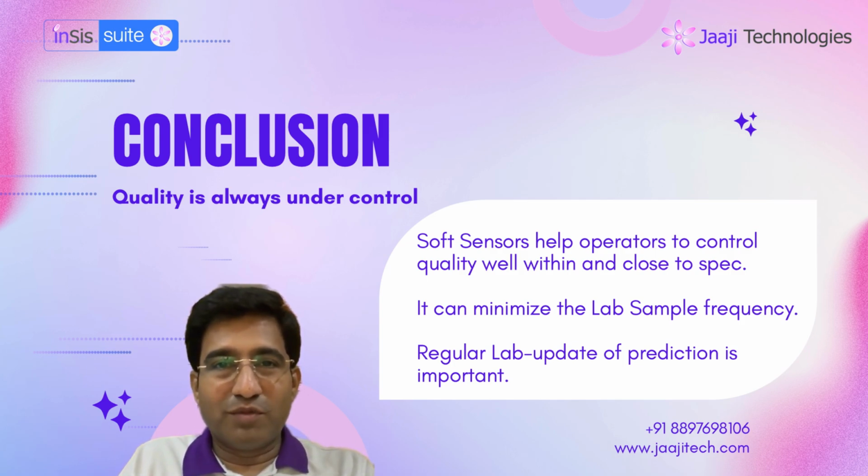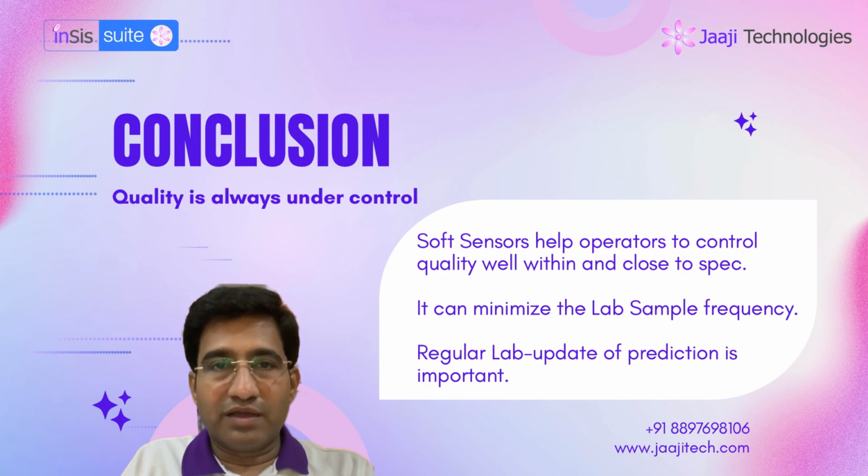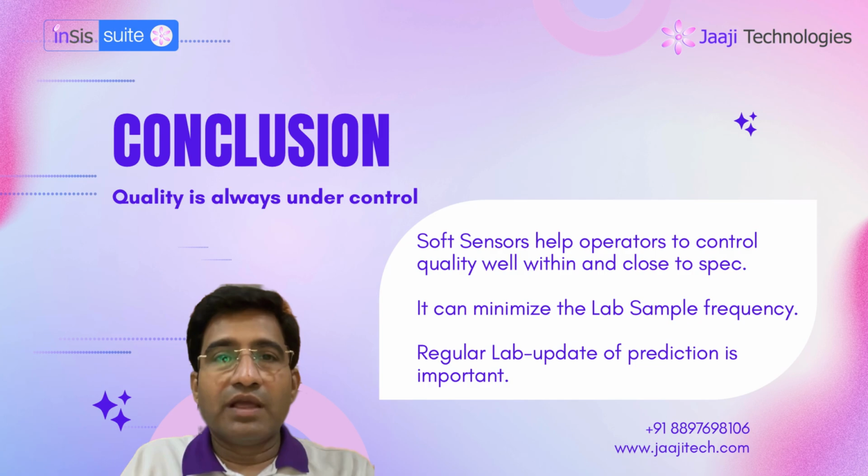So we have come a long way. We have learned what a soft sensor is, how it works, underlying technologies, methods and algorithms, platforms, and we've seen how to build it and deploy it using insys.ai. Now, to conclude the session, in order to effectively control the quality, soft sensors come very handy to effectively control the product quality. The accuracy of the soft sensor depends on how good the data quality is and how nicely the model is built by the chemical engineers or data scientists, and continuous lab update is important for ensuring that the predictions do not drift away from the lab data.